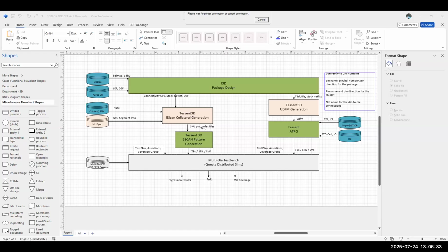I know in the old days we had bonding options. Is this for binning purposes or for different pinouts? It's for different pinouts. Different customers might choose DDRs from different directions of the package. Somebody might prefer the left side, somebody the right side interfaces. That is based on their PCB and platform design. Intel has this across all the data center products; it's their bread and butter. It's not only DDR, all the high-speed I/O and GPUs have the same flavors.